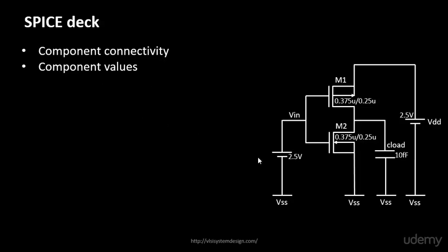So these are the component values that we are picking up. We have these values for PMOS, the values for NMOS, the load capacitor, and the input, output and supply voltage. Okay, and these are all the VSS terminals, so let's club the VSS together. We have this common VSS for all the supplies that is present over here. Okay, next step is to identify the nodes.